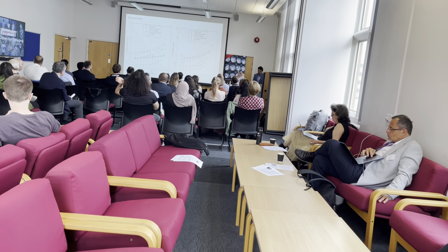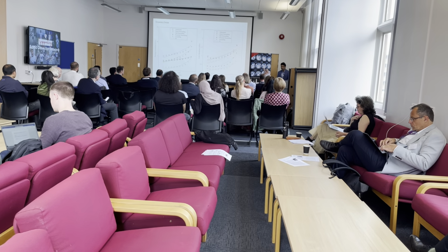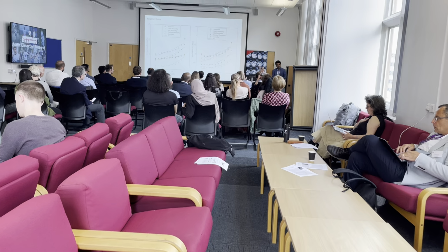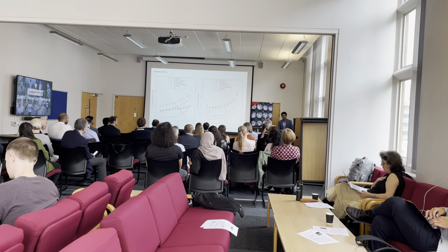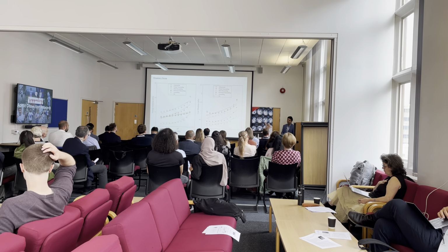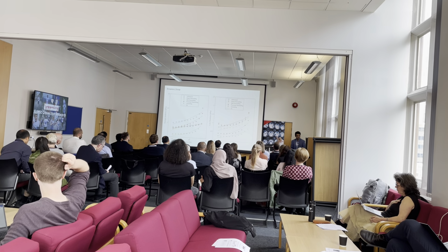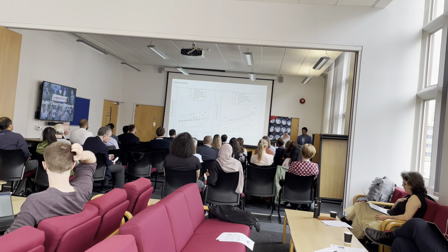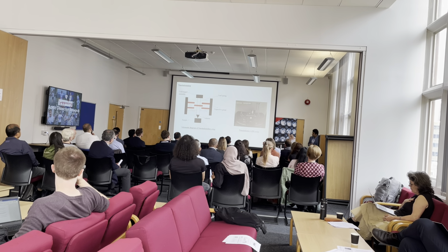When I tried fitting some of the basic models like the SLS model, the standard linear solid model, or the Maxwell model, or the Kelvin-Voigt model, they were not able to take into account this behavior as a function of frequency. There are some models, for example the Prony series, where you apply a series of springs and dashpots along with the Maxwell model. But the problem is that the computational expense goes up. So that was basically one set of the experiments.